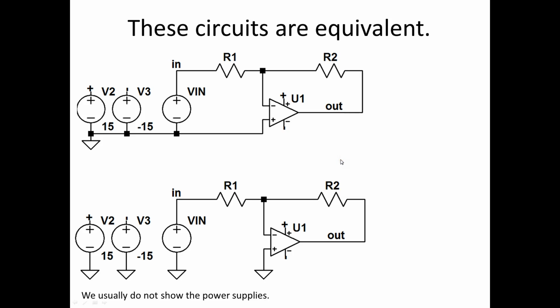Before we get started, just as a note of shorthand, these circuits are equivalent. Here, the positive pin and these sides of the voltage supplies are all connected to ground. Usually we don't draw the wire everywhere, and we just use the ground symbol here, here, here, and there. And many times we don't even show the power supply. So if you need help understanding that this ground and this ground are the same, just draw a connecting wire of 0 resistance between them.